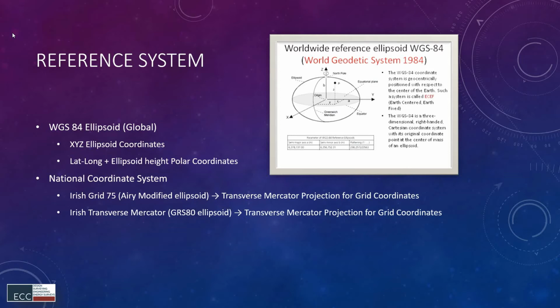After, if you want to use that survey for mapping, or you want to put it into a grid system, well, basically here comes the thing that all the maps are plane maps, so it needs a projection from a 3D object like an ellipsoid to project onto a surface which can be easily made a flat plane.